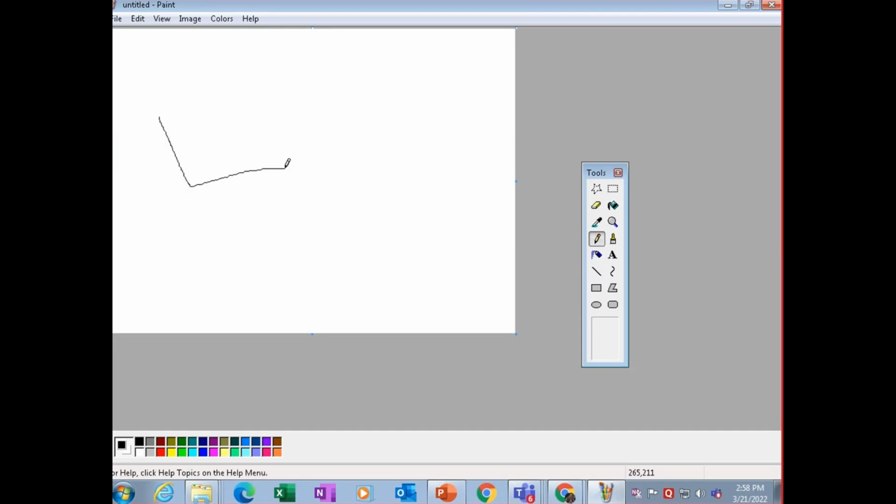Now, suppose a vessel is hogging. The tensile stress is coming here on the deck in hog, and a compressive stress is coming on the bottom plating. This is the compressive stress.